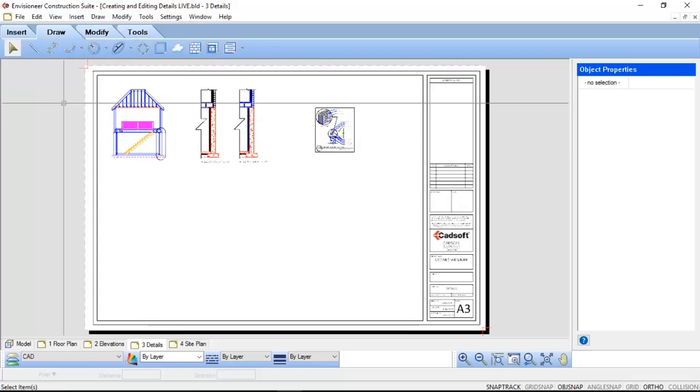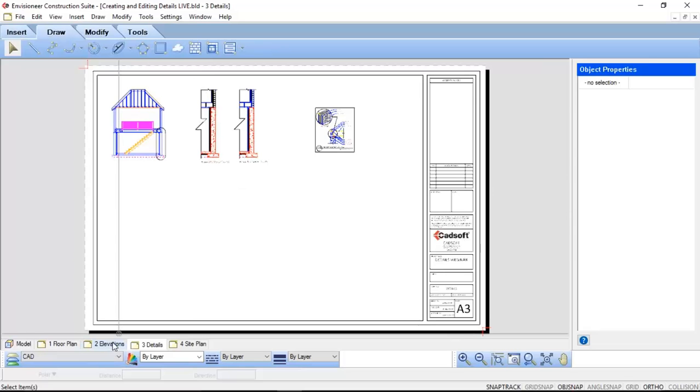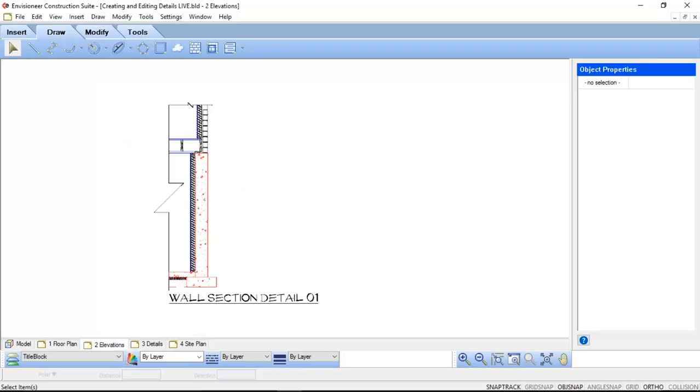We then learned about exporting and importing DWG and DXF format files. So to export, we go to File, Export, 2D Drawing, remembering that first we placed only our detail onto a worksheet all by itself and made sure there was nothing else on there that we wanted exported.